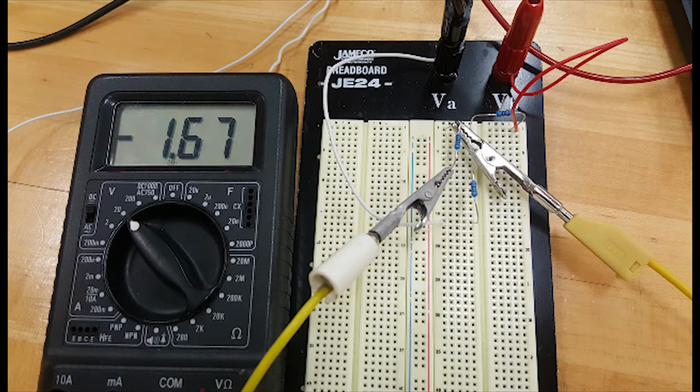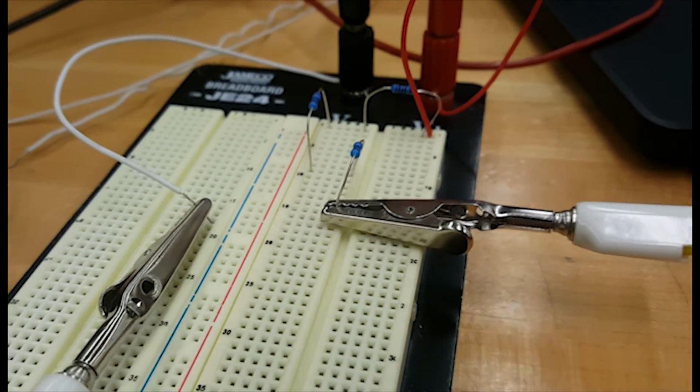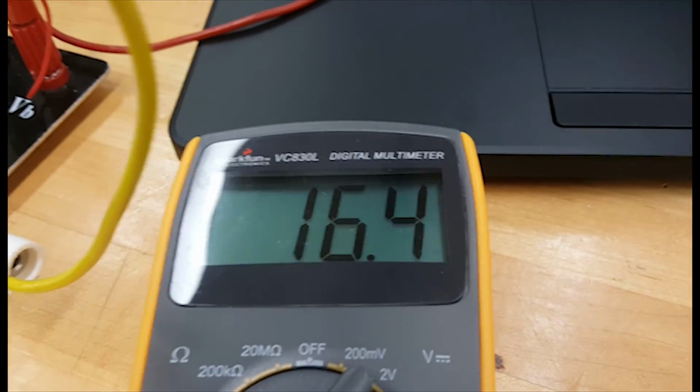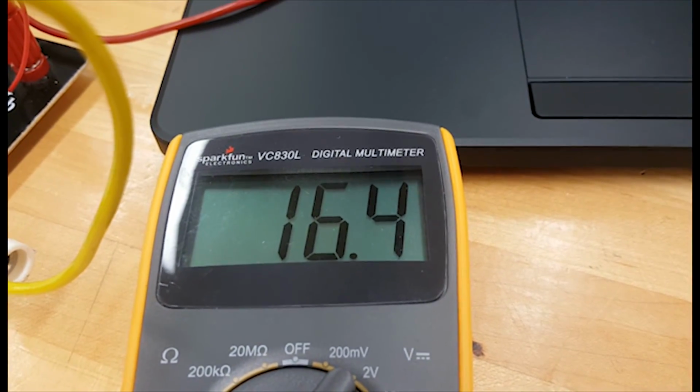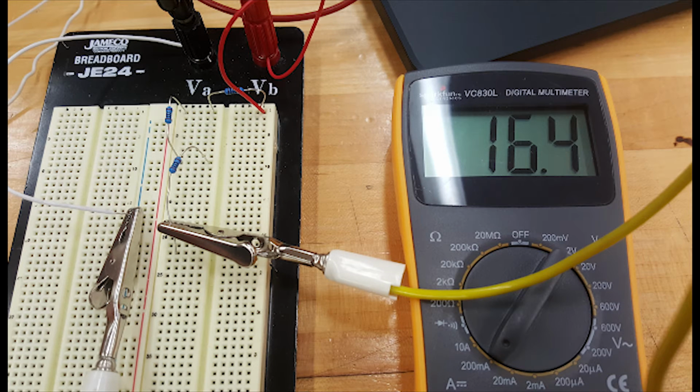So what we were doing here is we were actually measuring the voltage drop across the second resistor in the system. Remember about probably 6 minutes ago when Kaale was doing all that math, it turned out that that was the voltage drop that we calculated from the first equations. The short clip is how we ended up measuring current. We actually had to break the circuit, and we ended up getting 16.4. That 16.4 is in milliamps, so if you actually do the conversion, you get 0.0164 as your current going through that point in the system. So again, the numbers lined up.